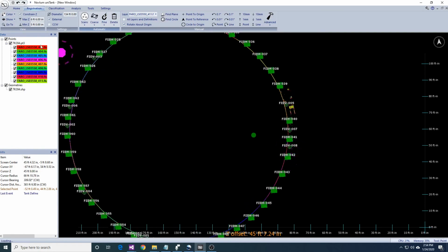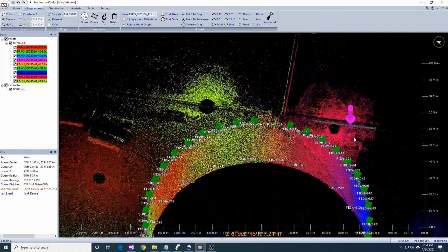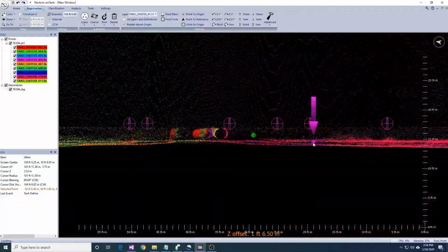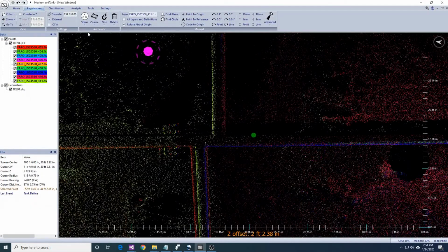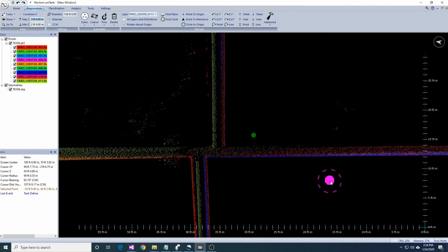I'm going to look at the ground level to see if we can find any other horizontal fiducial surfaces that may be suitable. Again, any smooth, flat surface that overlaps between scans can be used. This includes cars, containers, buildings, etc.